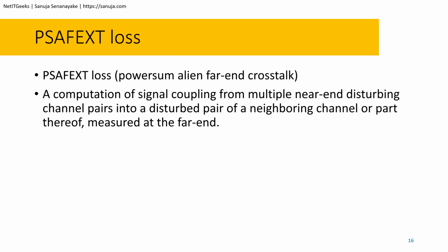PSA-FEXT loss, again Powersum alien far end crosstalk, which is basically a computation of signal coupling from multiple near end disturbing channel pairs into a disturbed pair of a neighboring channel or part thereof, measured at the far end of the cable, right?